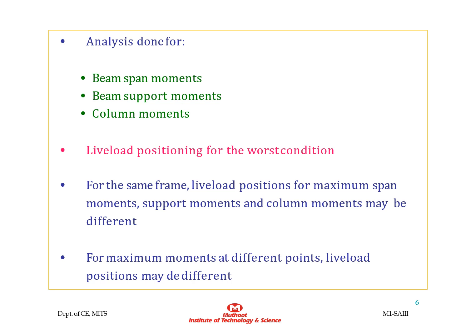In the multi-story frame, both dead load and live load together constitute the vertical loads. Dead load acts throughout the frame and at all times, but live load may act throughout the frame or on a part of it at a particular time. So for getting maximum moments, various combinations of live load are to be considered, because for the same frame the live load position for maximum span moment, support moment and column moment may be different.